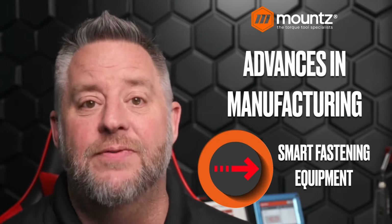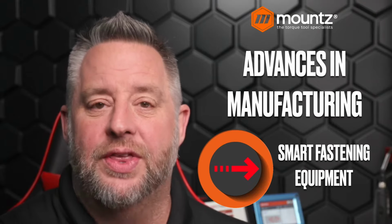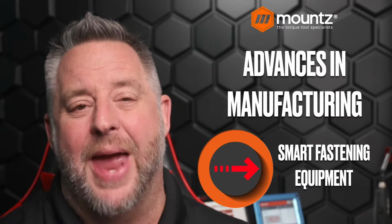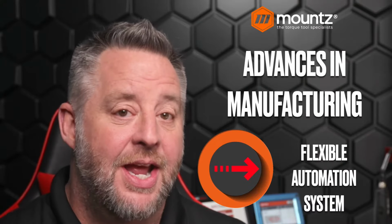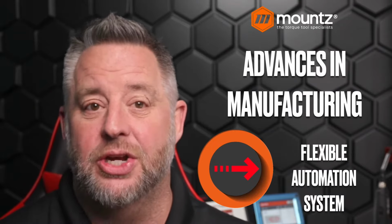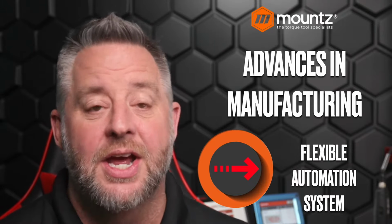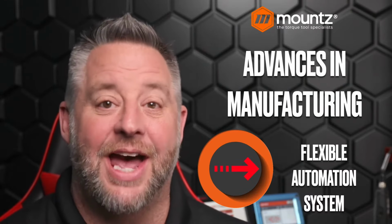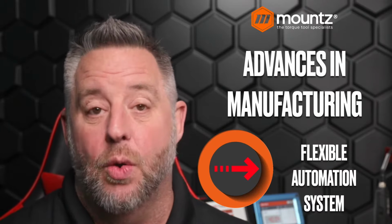The ability for the tools to communicate with line control devices, with the ability to control what happens during the rundown with the tool itself, has brought us to a place where we can have a lot of control about what's happening. And this gives us a great deal of flexible automation systems to be used, whether that is through an MES system and communication to that, through a PLC and other types of line control devices that allow us to have a lot more control and a lot more communication about what is happening with that process.